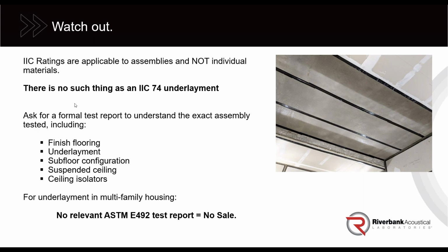So you'll want to look at the laboratory test report, which will give you specifications for exactly what was tested, including the finished floor, underlayment, subfloor, suspended ceiling, any isolators that were in place, insulation in the cavity, basically the whole buildup. This is very important. So, like I said, with floor ceiling assemblies especially, you really want a lab test report to verify that before you pay to have a flooring installed or you build a building, so that you know you're going to have a satisfactory performance.